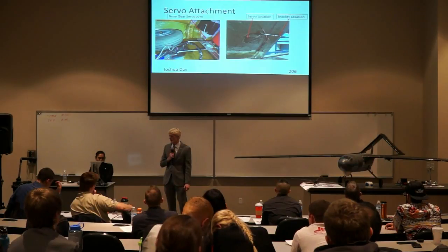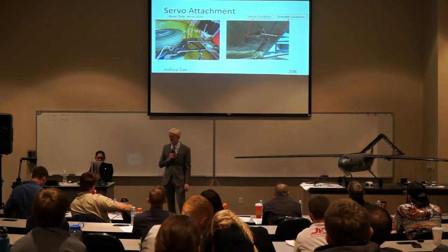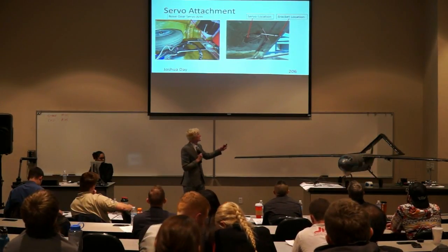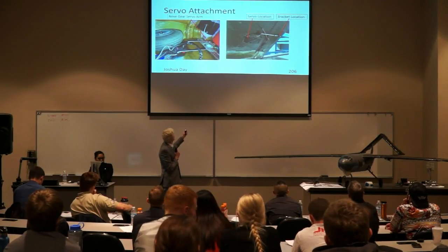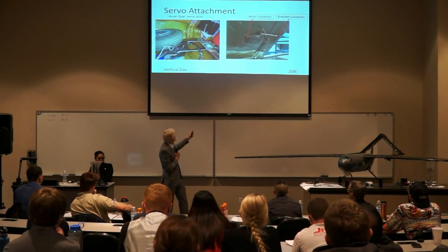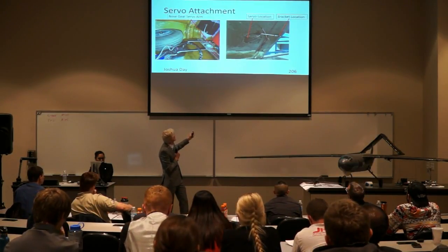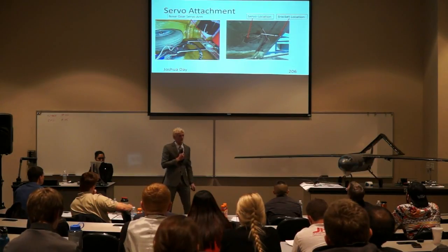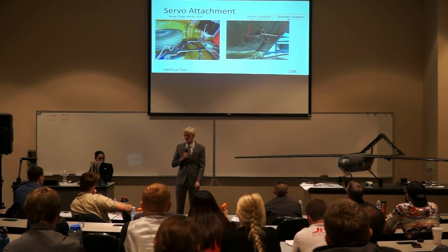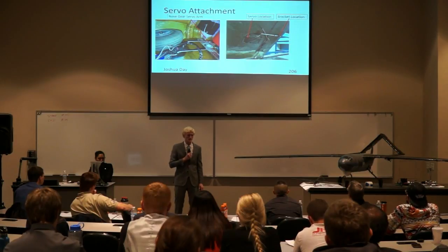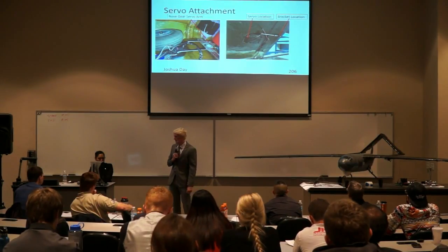The servos, as I mentioned earlier, were attached. As such, the servo to control the nose gear is shown here, and we created an aluminum plate and drilled holes in it to attach the servo and allow the nose gear to be rotated for control on takeoff and landing.